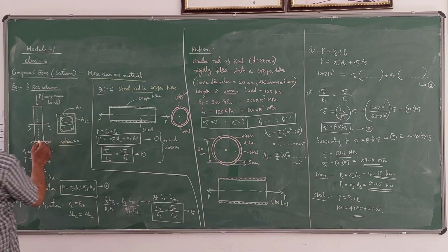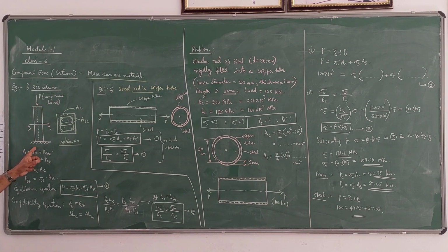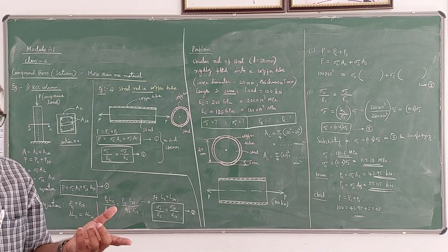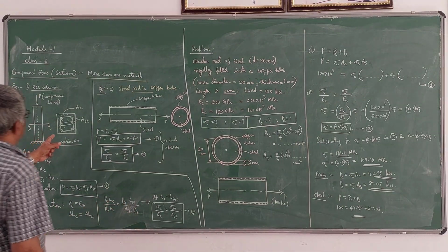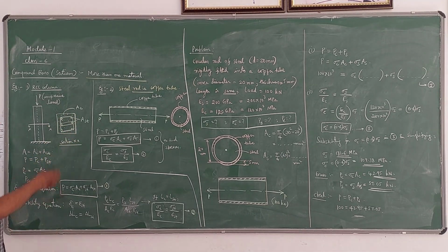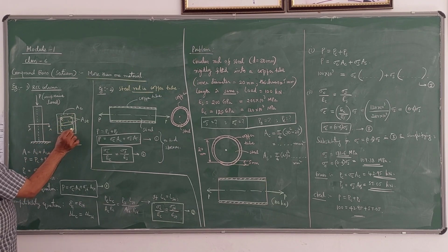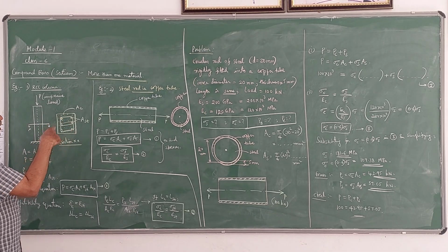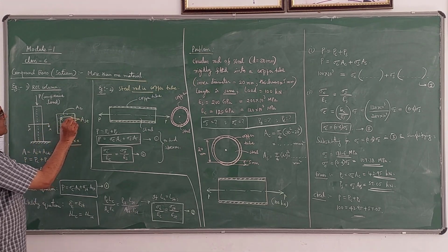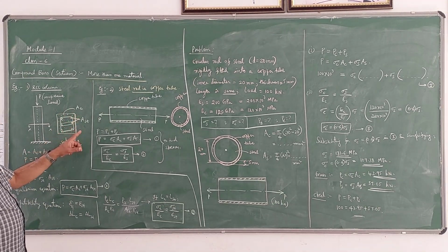So this is the cross section. The column is a vertical member which can transmit compressive force to the foundation. So this is the foundation. If you take the section of this column, it can be rectangular or circular or square, anything. Here in this example I have taken a rectangular column section, and in this section reinforcement is provided like this. You can see in the section the reinforcement as circular rods, circular sections. That I have taken as AST. AST stands for area of steel, and the remaining thing will be concrete. So both together is RCC.